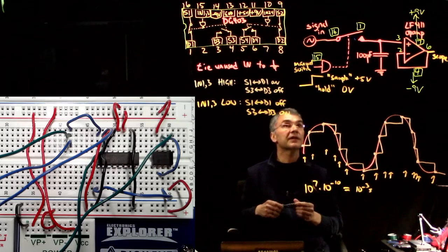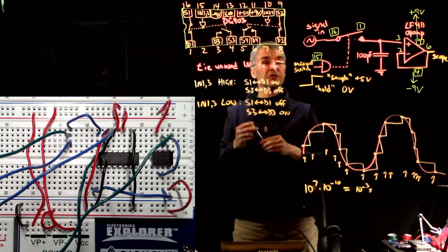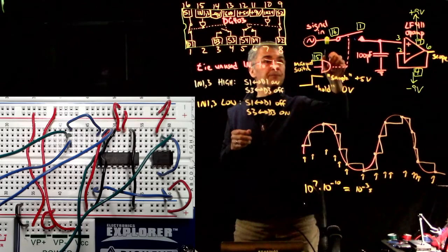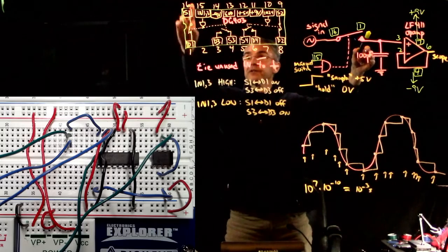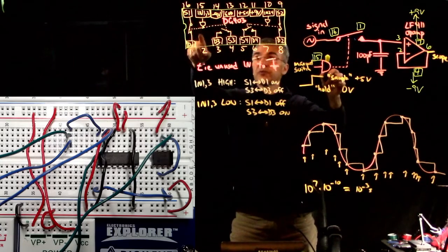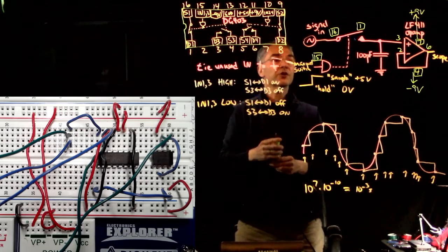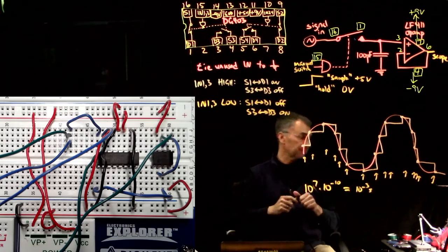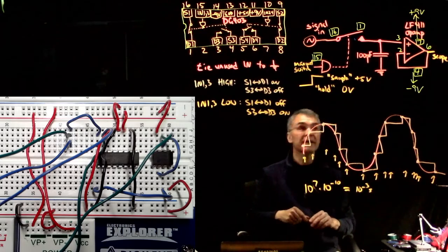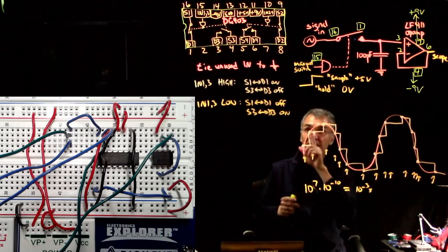And then we're using the DG403 analog switch. So here's pin 16 and pin 1. These correspond to this source 1, drain 1 switch here. And then the logic that controls the switch is pin 15. This says use a manual switch. I thought it was more interesting to use a waveform generator. And I wired this up, but I forgot the capacitor. I'm going to fix that.